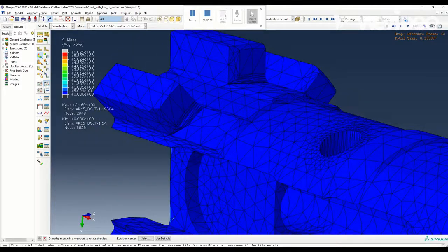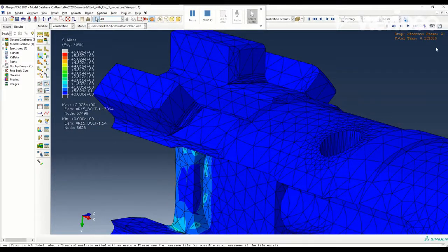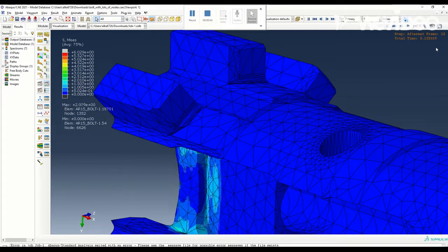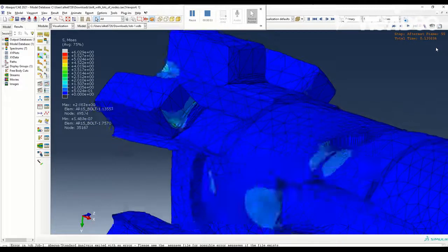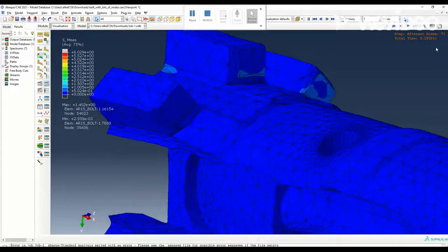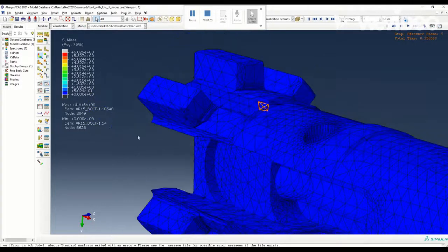Now zooming into one of the most key aspects of the part, the locking lugs, we can see how well this part is designed. All the chamfers and fillets on all the parts allow that the stress is not concentrated in all the corners.